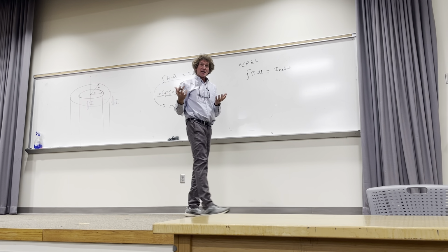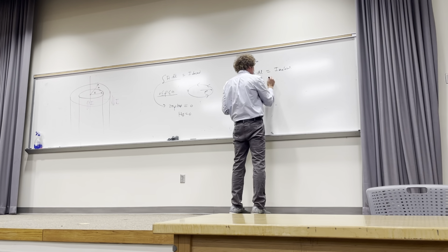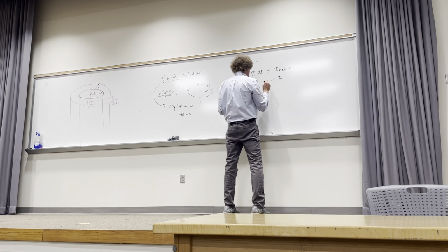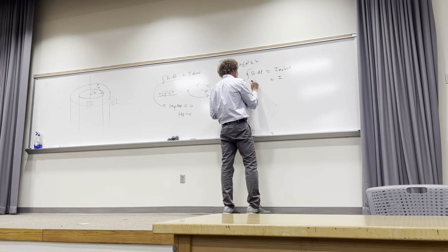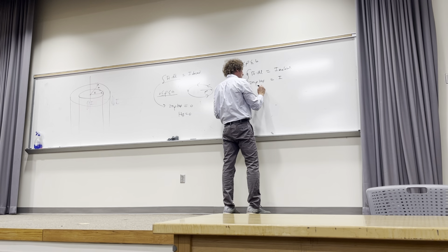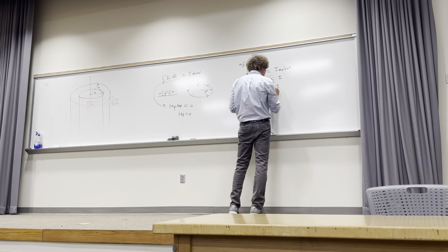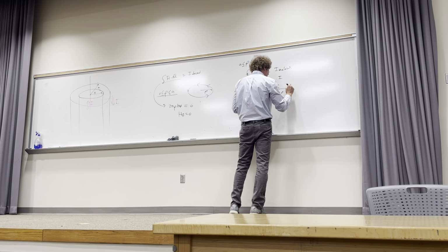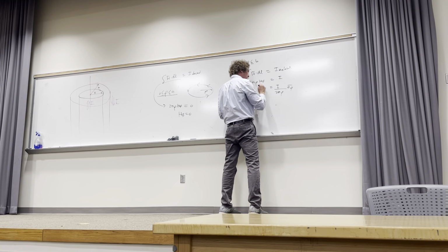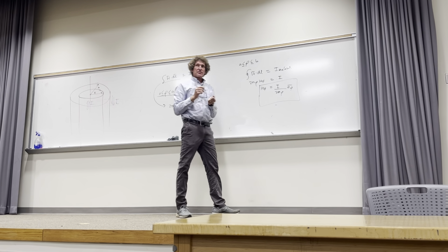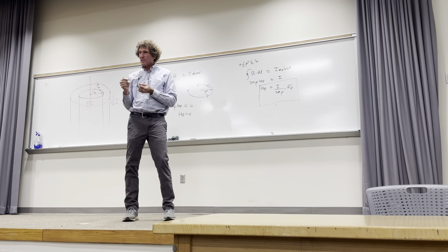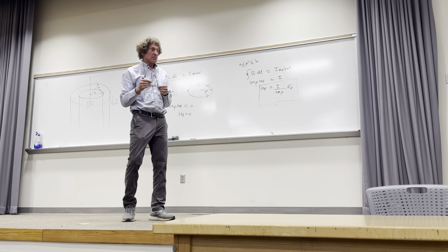So it's just I, it's just 5 amps here. And this is still 2 pi rho h phi, and therefore h phi is equal to I over 2 pi rho. You can put a phi direction, but I didn't even ask you for that. I'm just asking for a magnitude plot in a second. Y'all with me? So that's that range.